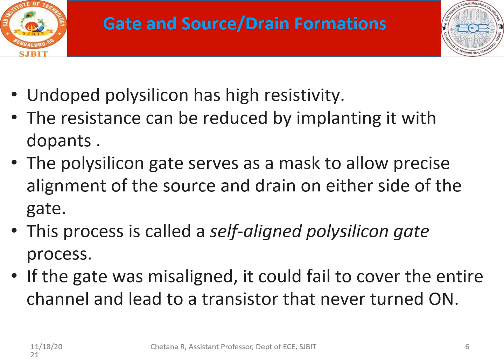However, this resistivity can be brought down by adding the necessary dopants. And the polysilicon gate sometimes acts as a mask for the diffusion to happen.